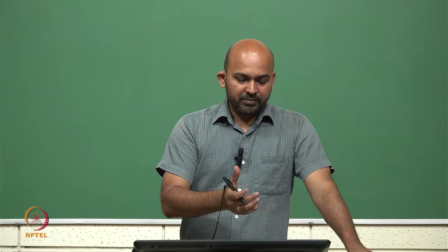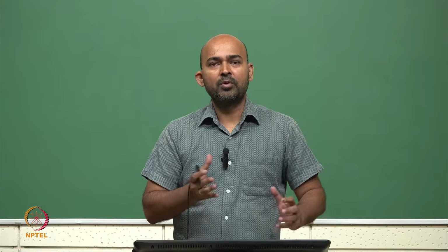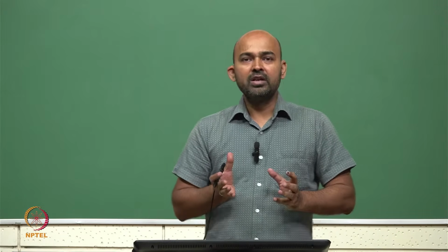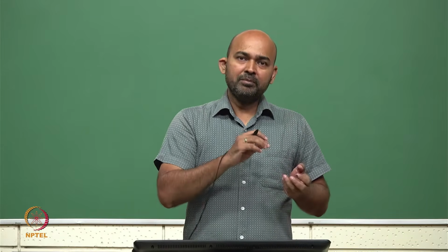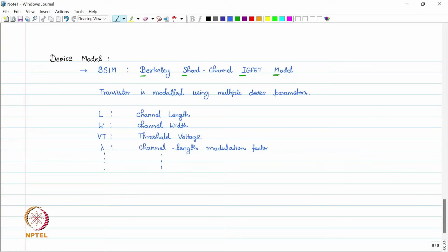So this BSIM is nothing but the set of parameters which are generally provided by the foundries who are making these MOSFET devices. These foundries make the MOSFET on silicon. They measure the electrical parameters and geometrical parameters and put them together in a set of equations, something called the model for the device.